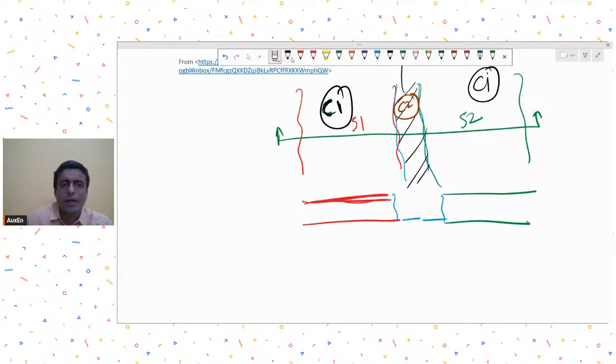Technically, I would like to do this pour strip in one cast, but let's say due to some unavoidable reasons you are not able to cast it in one go. Then instead of leaving a vertical joint, leave a joint slanted at around 45 degrees. Because of this slope, the shear transfer between the old concrete and the new concrete in the pour strip will be more effective.